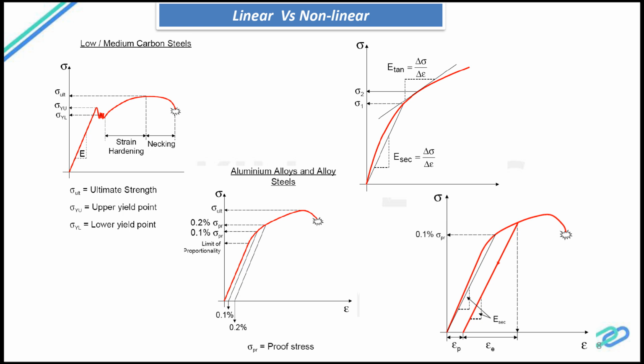It's very difficult to make out from this. It's just a curve in which you can see that even the linear elastic region is not a perfect straight line. So that means it doesn't exhibit any linear elastic region. So for these types of materials, the entire stress strain curve itself is something like a nonlinear curve,